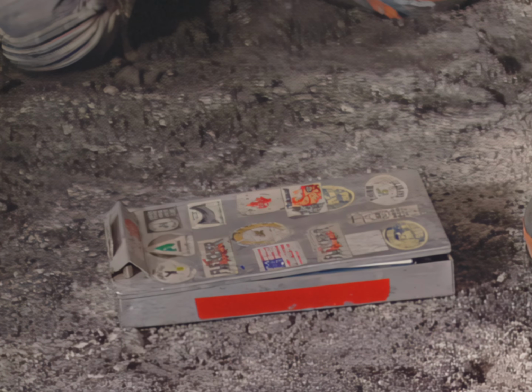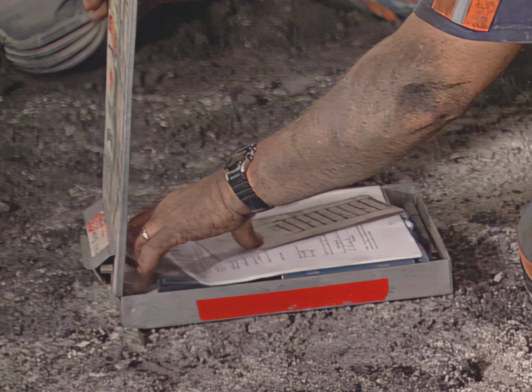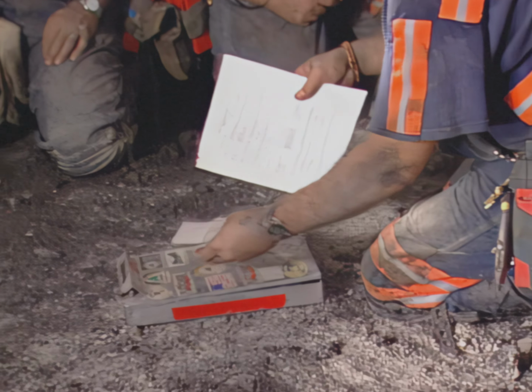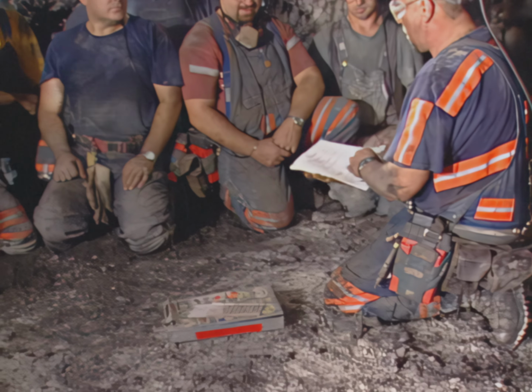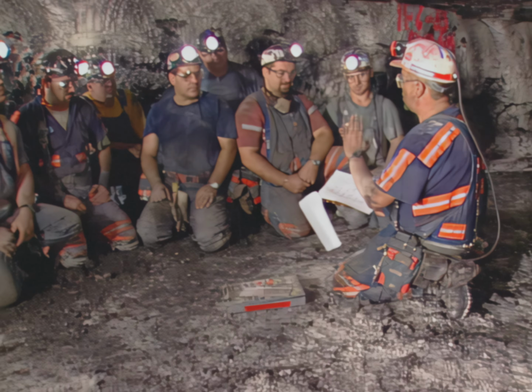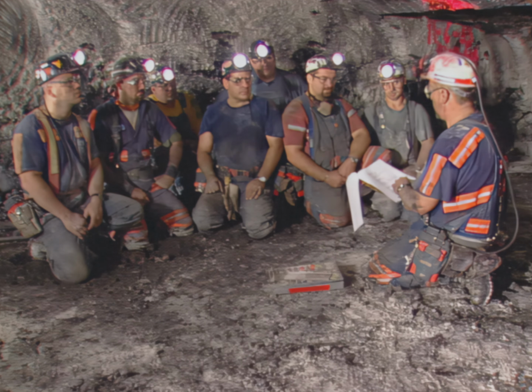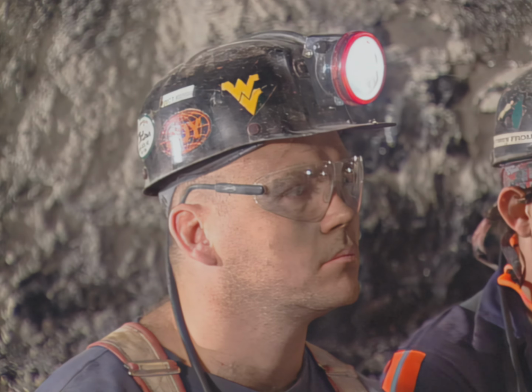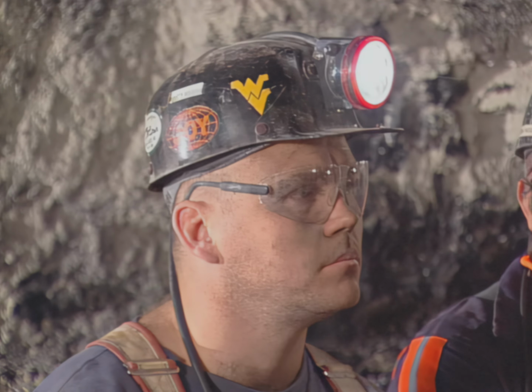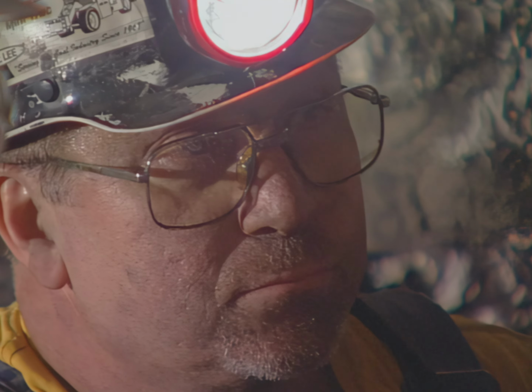Your mine's roof control plan tells the minimum that has to be done under normal conditions to support the roof. You've got to know and follow your plan's requirements. If you fail to install the proper supports required by your plan, then the roof is inadequately supported and you have jeopardized the safety of yourself and your fellow miners.